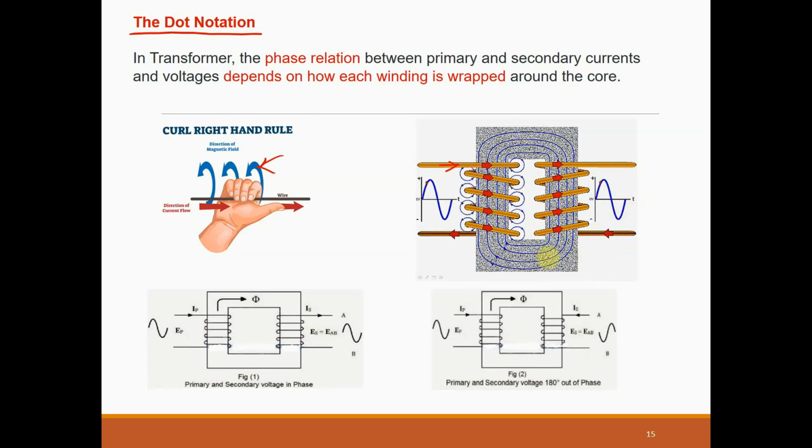Okay, how does the polarity of the transformer become opposite? It depends on the winding. Look at the winding here. It's entering from this point, and look at the output side. It is from this point, right? If you have a winding that is entering from the other side, that is reversed. That will be reversed. So let us have a clarification on that.